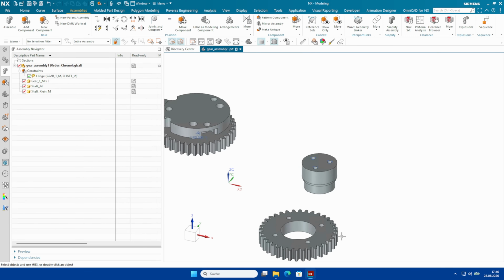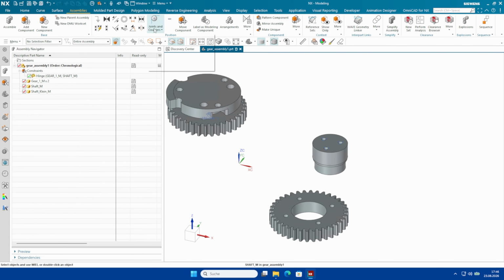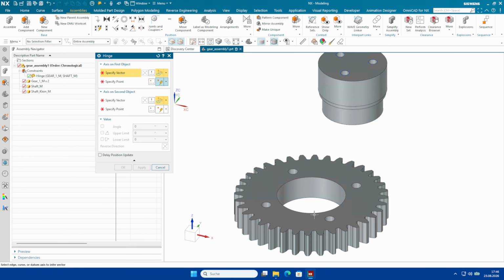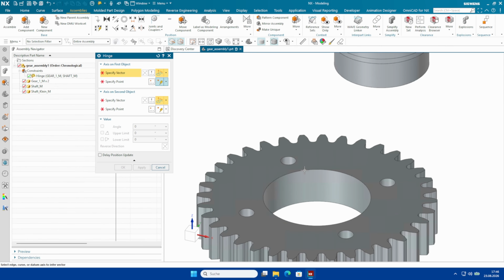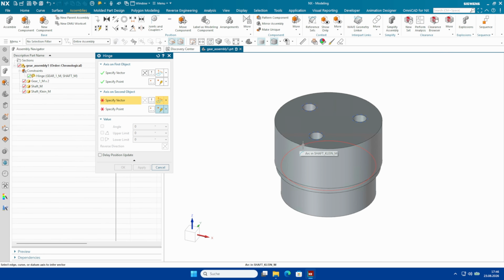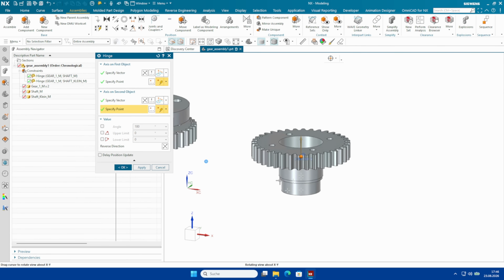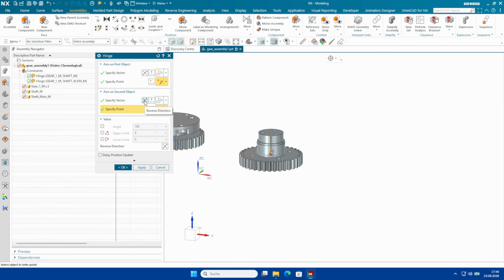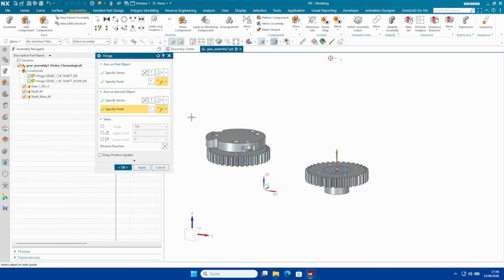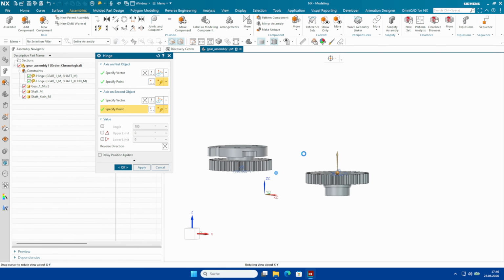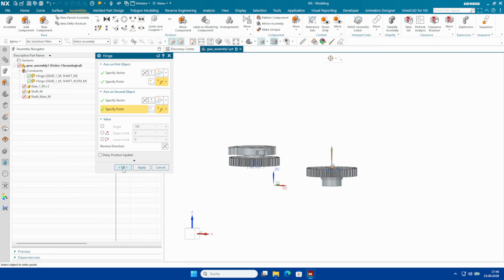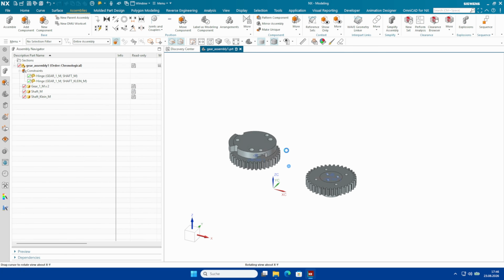After doing that, you're going to take a second hinge here and do the same thing for the second gear. So select this, select the same edge, that is done. For the shaft, select this edge, select this edge. So this is going to slot in there. Make sure you do not select anything; align, you can align it here as well. I'm going to align it however I like. So I want to align it this way. The shaft is this and this shaft is that angle upward. So I'm just going to click OK here for now.